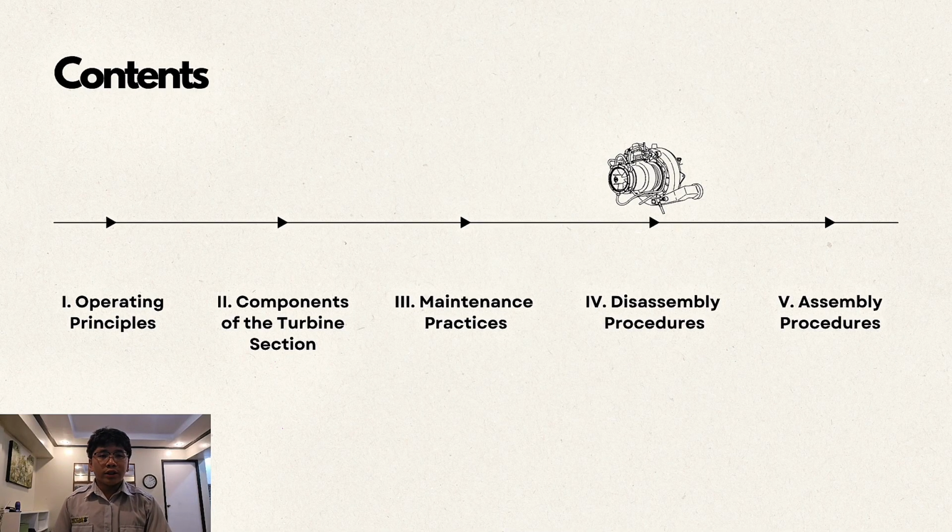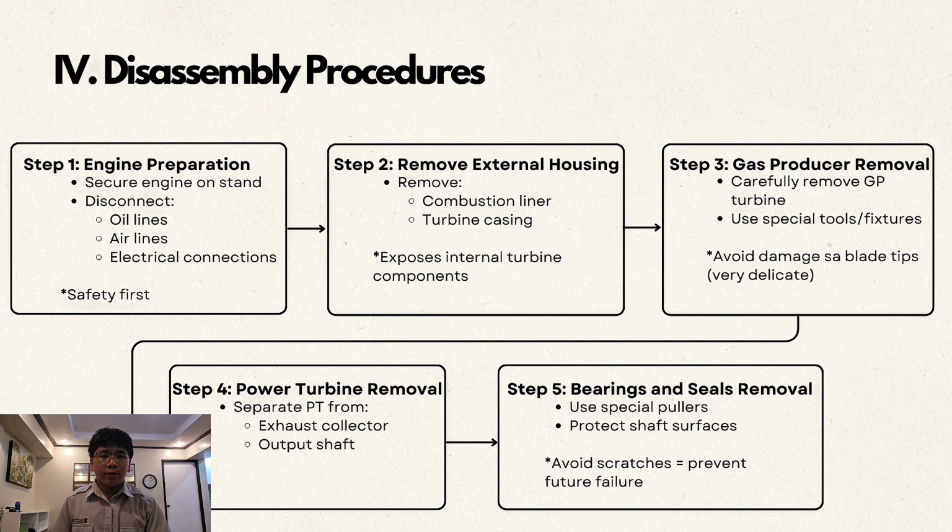Now moving on to disassembly procedures. Step 1, we have engine preparation. We begin by preparing the engine for safe disassembly. First, the engine is securely mounted on a stand to prevent any movement.